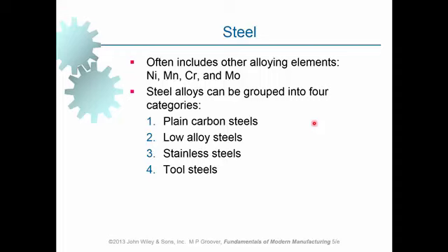They have got to be tough as well. Also in tool steels, we make use of quality steels, and also we make use of large amounts of alloying elements in order to enhance the properties of the material. By the way, it has to maintain its hardness. Tool steels need to maintain their hardness at elevated temperature. And tungsten and some other alloying elements are also added to enhance this property.